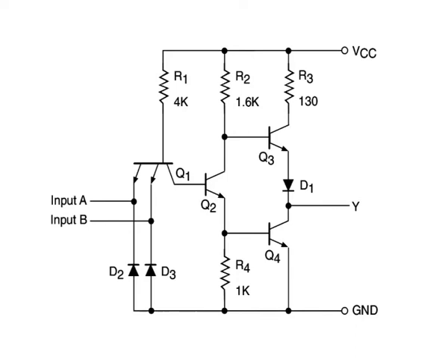Standard TTL. The figure here shows the internal schematic of a standard TTL NAND gate. It is one of the four circuits of 5400/7400, which is a quad 2-input NAND gate. Transistor Q1 is a 2-emitter NPN transistor, which is equivalent to 2 NPN transistors with their base and emitter terminals tied together. The two emitters are the two inputs of the NAND gate.